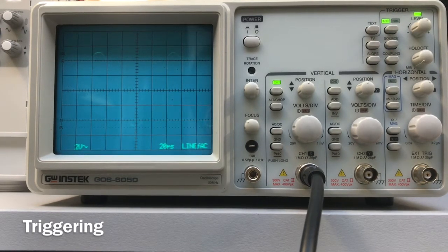This is useful when the waveform display is time related to the AC power source frequency, as you can recognize noise produced by the AC power source. And then the external mode uses the external signal to trigger the signal you're projecting on the screen, which is here.